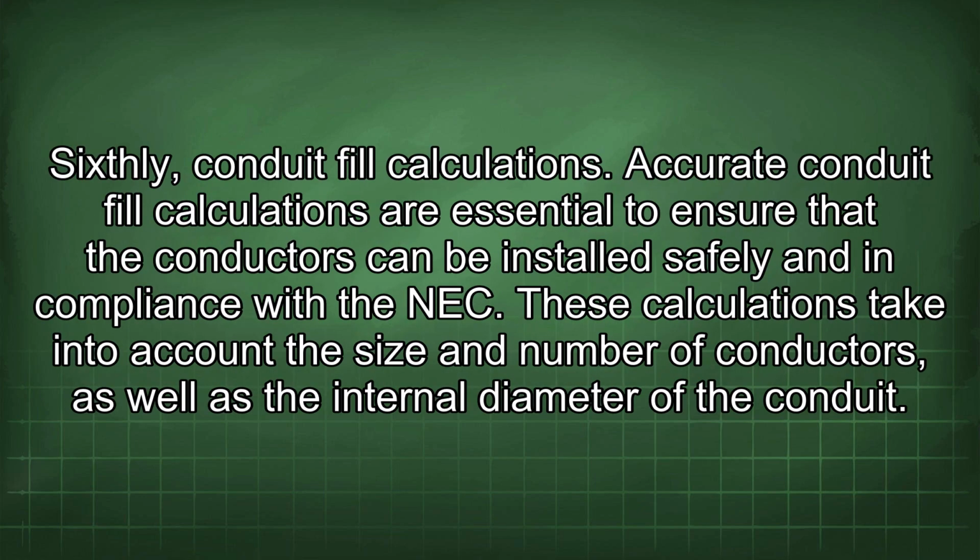Sixthly, conduit fill calculations. Accurate conduit fill calculations are essential to ensure that the conductors can be installed safely and in compliance with the NEC. These calculations take into account the size and number of conductors, as well as the internal diameter of the conduit.